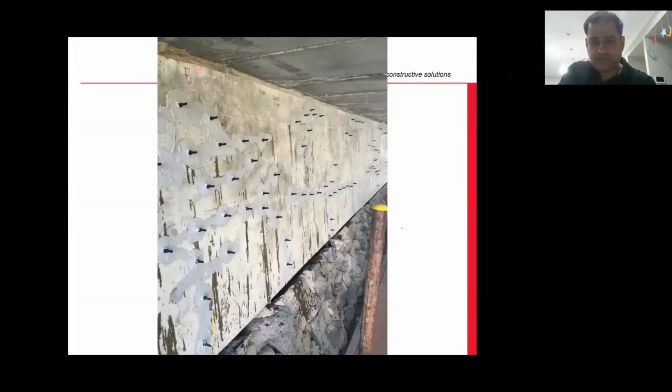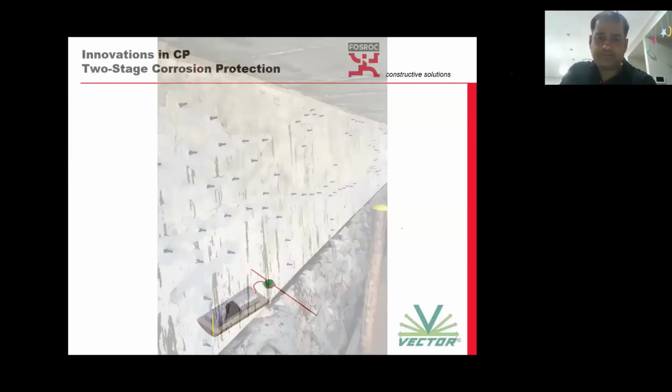For injection, we have complete methodologies of how to do injection and how deep you have to go, what type of depth of packers should be used if you are using mechanical packers. But for epoxies, normally you use surface packers. And I'll go through that in maybe next session sometime, only about injection. For polyurethane injections, when you have water leakages, you use mechanical packers. You drill holes at 45 degrees and inject it. For epoxy, because they are low viscosity, like water, you can use your surface packers.